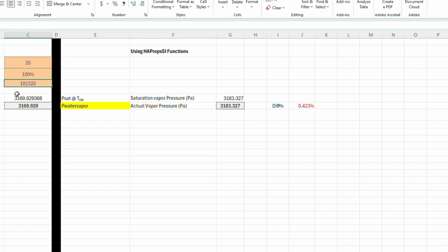then the saturation pressure is calculated using this PropsSI function. Okay. In here, you can see I have selected a quality of 1. I could choose a quality of 0.5, 0.2, any of those. It's going to calculate on that saturation curve. So if you give the temperature and a Q value, it'll give you the corresponding saturation pressure.